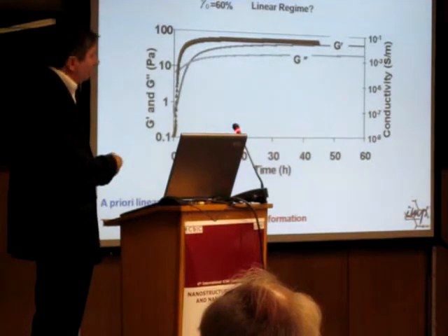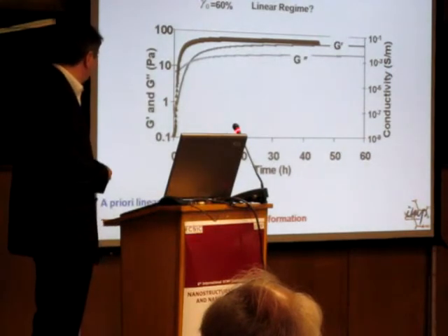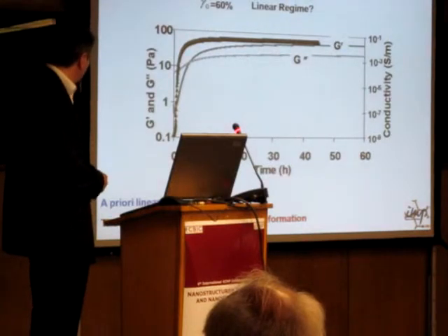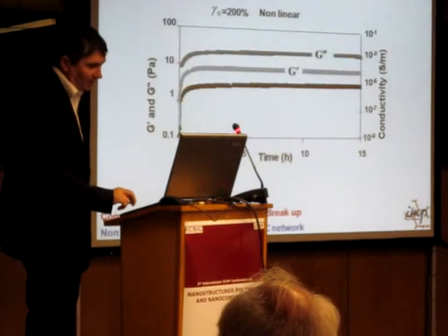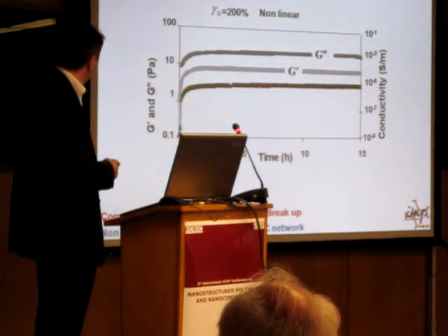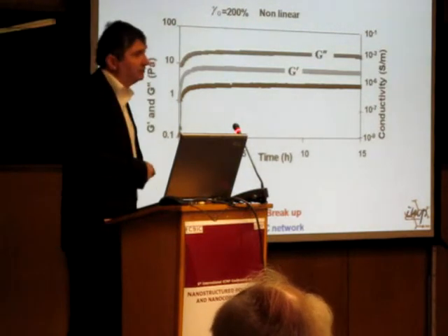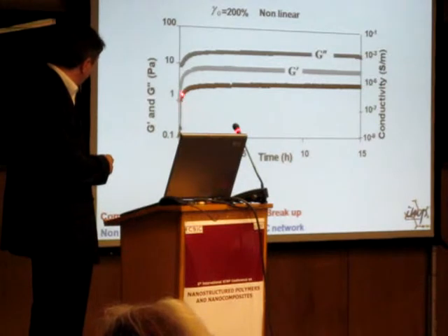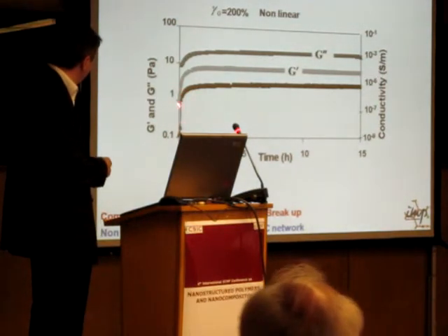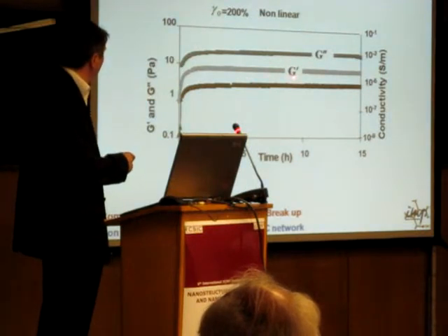So we admit that this variation is due to the network formation from the nanotubes, but the aggregation kinetics depends on the deformation. At higher deformation, here 200%, at this deformation I am sure that I am in a non-linear regime. The kinetics of aggregation is accelerated. The characteristic time is a few minutes, but we have a small variation of the conductivity and the complex shear modulus.